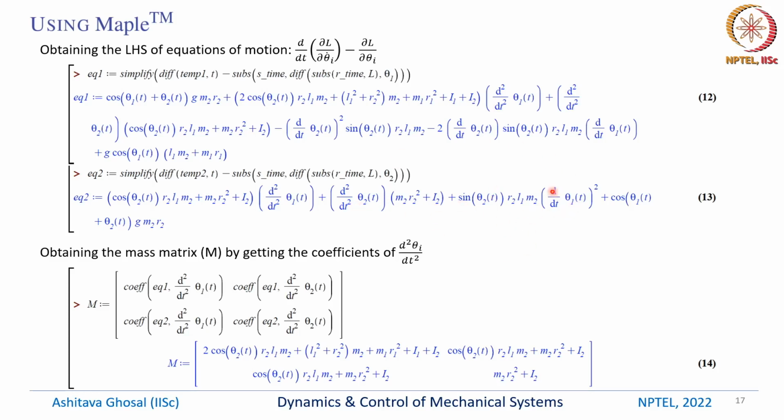So these equations you can obtain using Maple by simply taking the required derivatives, partial with theta i, partial with theta i dot, and d by dt of this part. And then of course you have to simplify. So you need to get used to it, try it a few times, and then you will see that it does make sense. It is not the way we write it by hand, because we would write M2 L1 R2 C2, but here Maple's text output is in some sense in the opposite way.